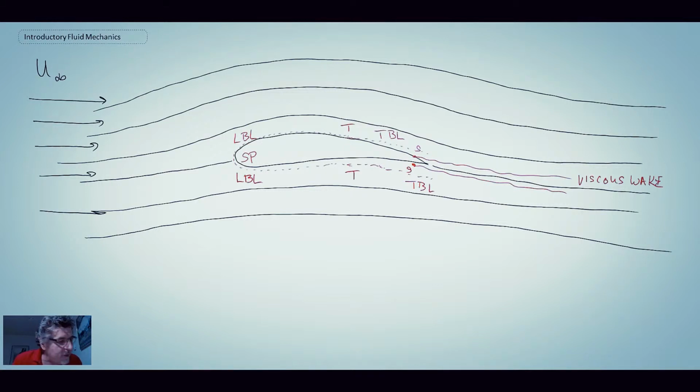so what we have in this flow field, we have a number of streamlines coming around an airfoil. And there is development occurring on the airfoil. Beginning, we have the dividing streamline, which hits the stagnation point where the velocity is zero. And the flow, some of it goes above the airfoil, some of it goes below. But if you recall the no-slip condition, we have zero velocity along the surface of the airfoil. And consequently what happens is there's viscous diffusion taking place, and the region of reduced velocity is what we refer to as being the boundary layer.